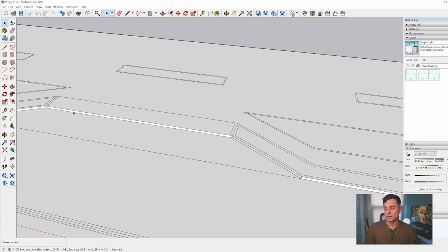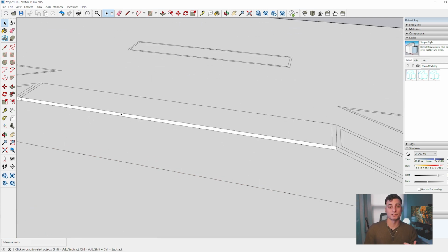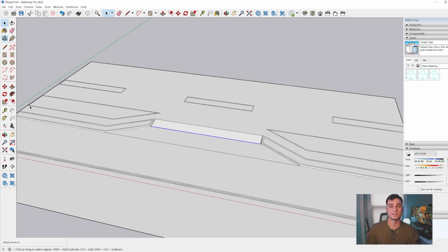So to drop down the ramp, you're gonna first need to select the top edge of that curb or that line, and then use the move tool, and then select it from the midpoint here, and then we're gonna hit the down arrow key on the keyboard and move it down till it's flush with the grade below, and then you'll have your nice and easy ramp.